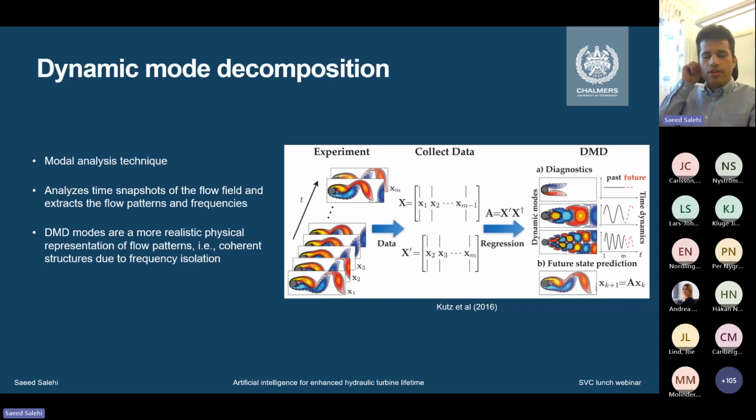The important part is that DMD, unlike POD, focuses on temporal orthogonality, which means that each DMD mode oscillates with an isolated frequency. That means DMD modes are realistic physical representations of coherent structures, unlike POD modes, which are more like mathematical representations of data. They don't necessarily represent any physics.